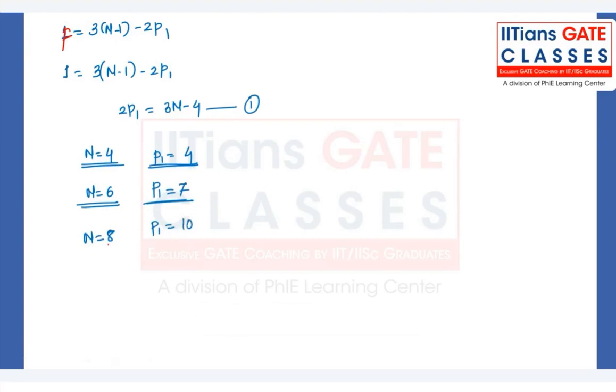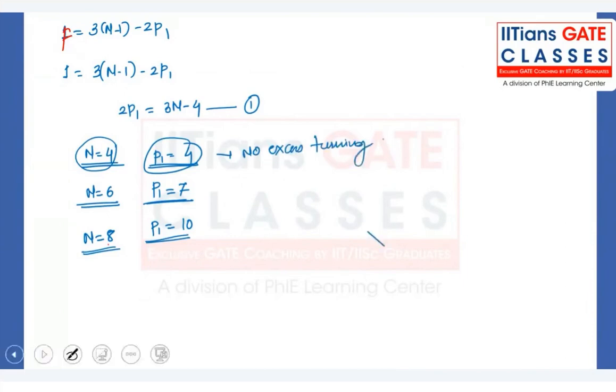We can understand from this that if we have 4 links, we have 4 pairs, so we don't have any excess turning pair. If we have 6 links, we get 1 excess turning pair. And if we have 8 links, then we have 2 excess turning pairs.